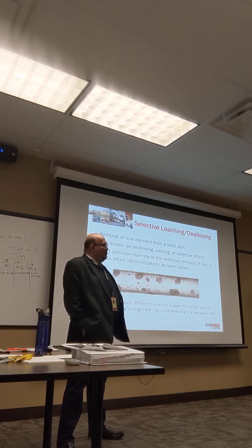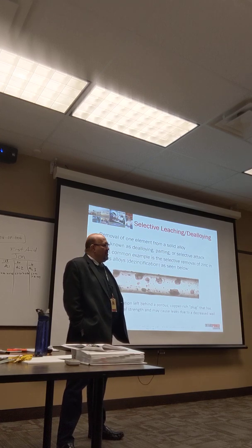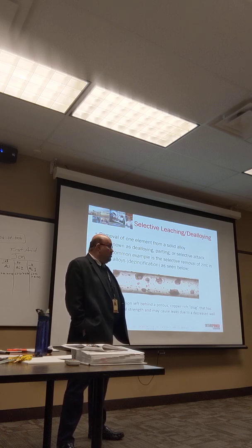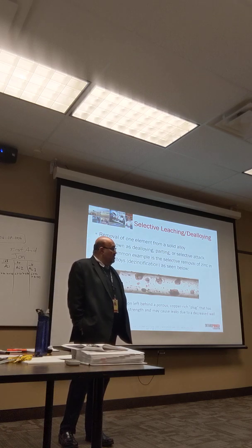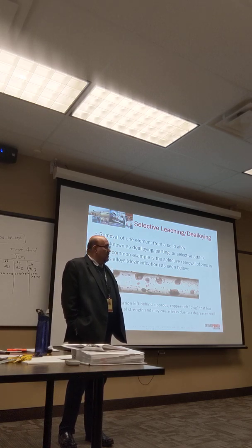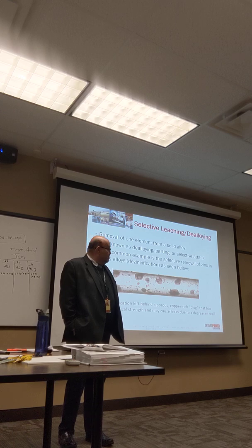These pumps only run very limited hours during operation. They run a bit during outage, but because of selective leaching removing the cobalt from the rings, we get seal leaks developing all the time. So that's an example of selective leaching that's a problem we haven't been able to solve other than replacing parts periodically.